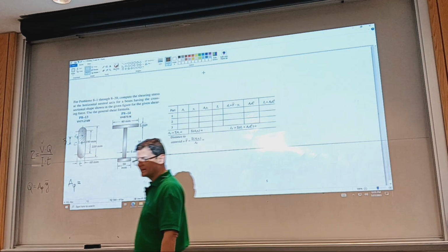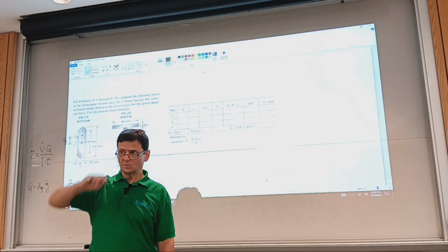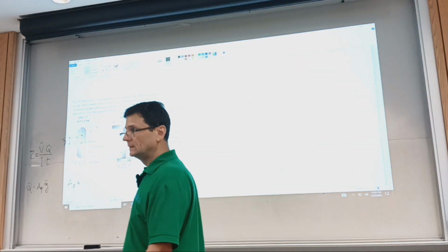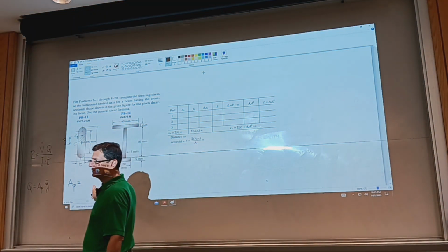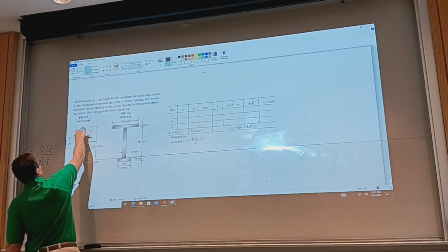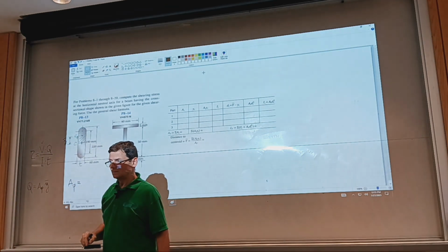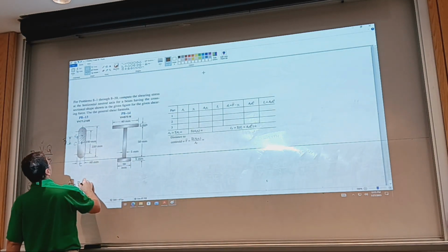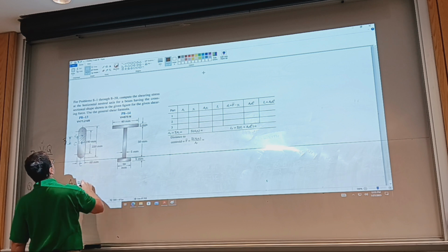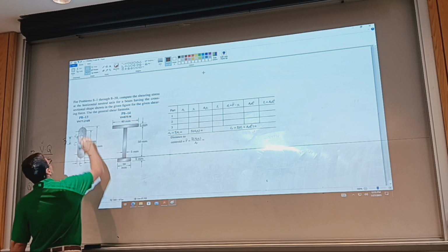What's the partial area? Looking at the figure, what's the partial area? You don't need big-deal maths to write that down. Who wants to help? It's made of two sections, a rectangle and half of a disc. Is that right? So I'm going to have half of 190 times thickness, so it's 95 times 60, and that's for the rectangle.